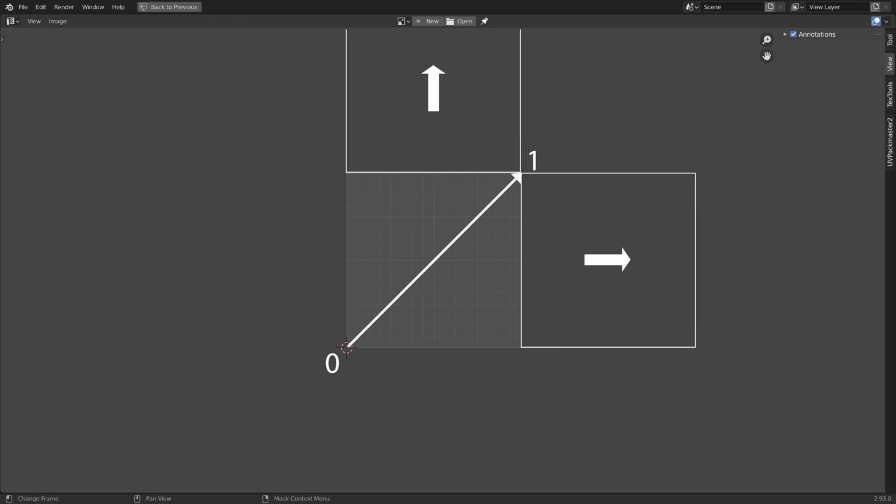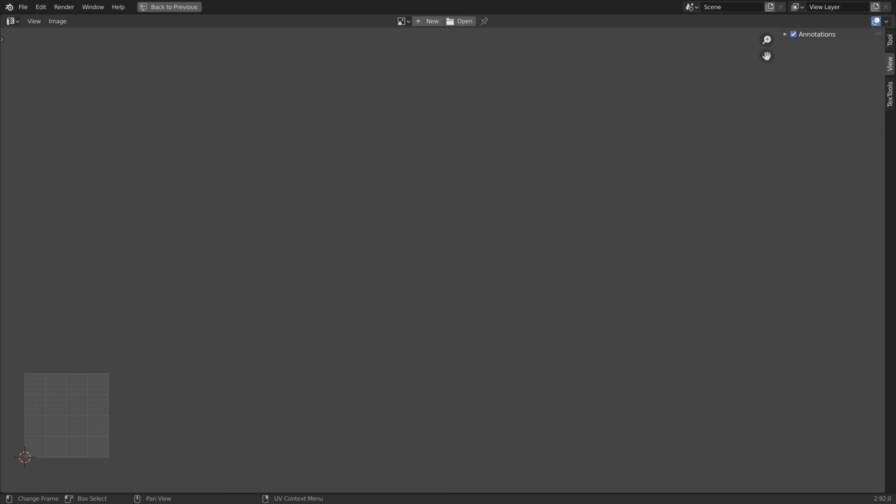By creating an offset of the original 0 to 1 UV space, we refer to this offset as a UV tile. Each UV tile has a number, and this number changes according to the position in the UV space. And each tile can contain its own image texture. In the UDIM workflow, the first available tile is labeled as 1001.